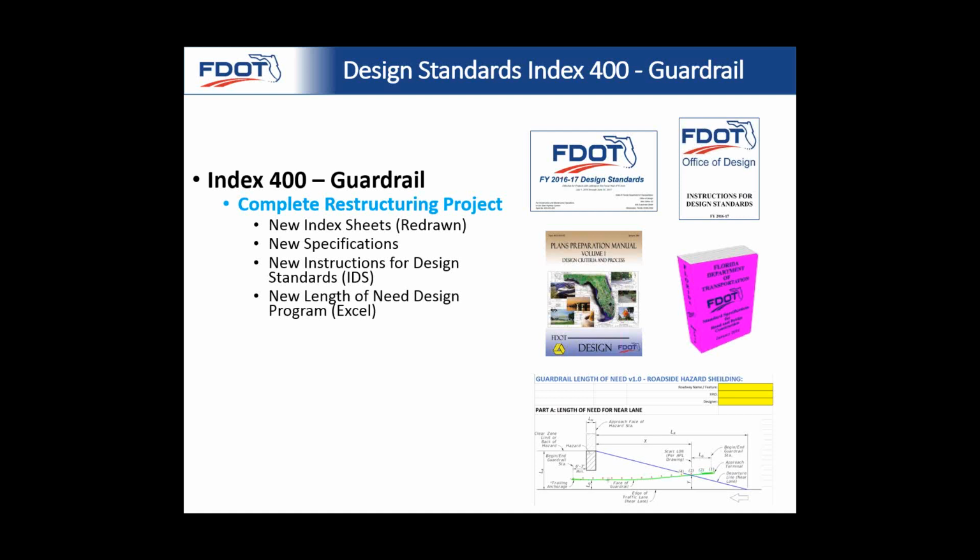We're going to touch on each of these subjects a little bit more in depth. We have a new Length of Need design program in Excel. Here's a little snapshot in the lower right-hand corner of the idea of length of need. Basically, it's telling you how long your guardrail has to be designed to shield this hazard successfully. In the past, we've had a really simplified process, and it had been overly conservative in a lot of cases, and in some cases, it wasn't providing enough length. So we really need to step up to the latest national standards of AASHTO and design guardrail to the optimum length that's the most efficient.